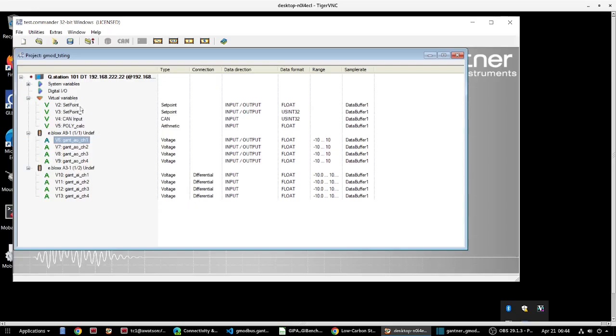Now, I don't think that you're going to be able to talk to these using eBlock server. Maybe you can and you've figured it out. I never tried because I don't love the attribute layer to begin with. So these you can read via the default underscore eBlocks if eBlock server is running. They'll just stream by default, but you can't write to those using that method. So what you can do is write to them using gmodbus.